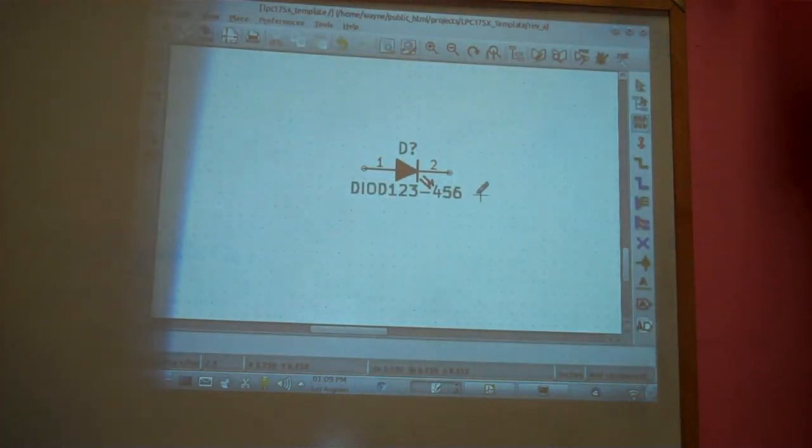Okay. So the other thing we want to do is you want to be able to draw wires. Wires are over here with the green thing. So we click on the wire, and we're just going to draw. Let's see. I just hit the escape key. Whenever you make a mistake, escape brings you back to where you wanted to be. Okay?